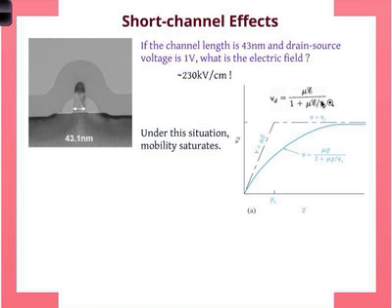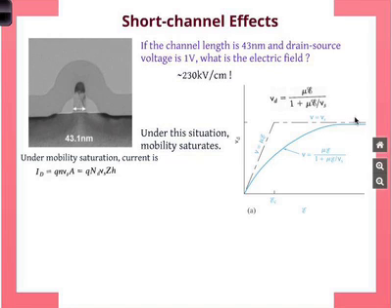Now, to solve this is relatively easy. You plug this into the calculation for the resistivity and just redo the equations. The integral changes a little bit, but other than that, it's not that different. In between, it's a little complicated because you have to do the integral. For our purposes, we'll only study two regions. We'll look at the linear region, which is what we just did, where mu was constant, and we'll look out here where there's saturation happening. So again, essentially, the velocity is a constant.